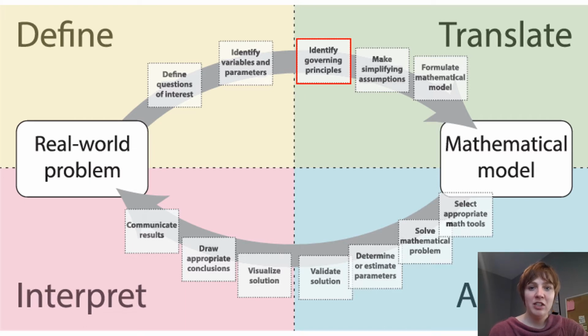In hydrogeology, we typically start with conservation of mass or energy, but mass is easier to measure. We also utilize Darcy's law, the equation that states that discharge, the volume of fluid traversing a cross-sectional area per unit time, is equal to the hydraulic conductivity of the material multiplied by the change in head across the volume of interest multiplied by the cross-sectional area of the discharge outlet.